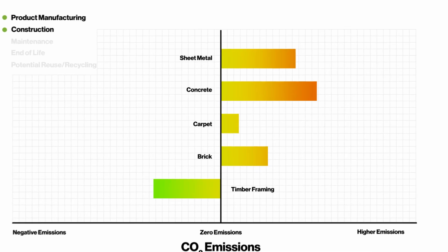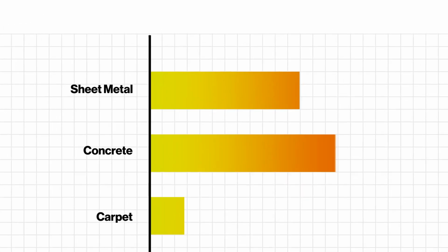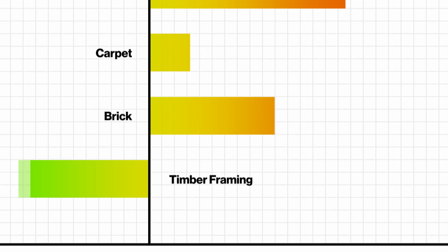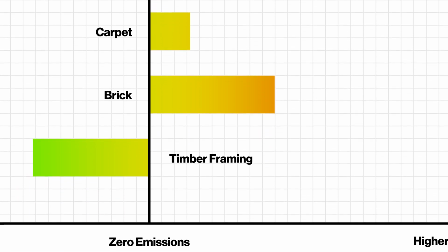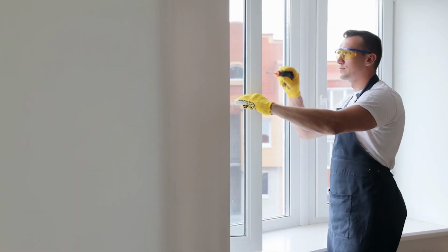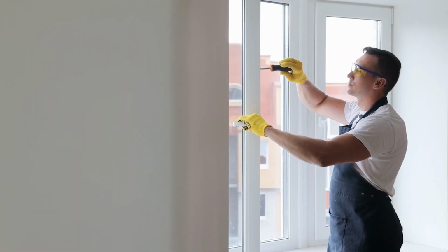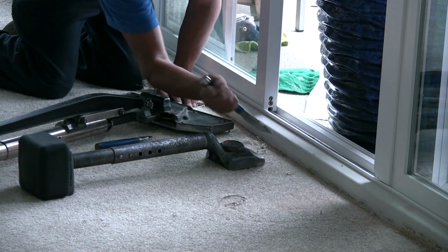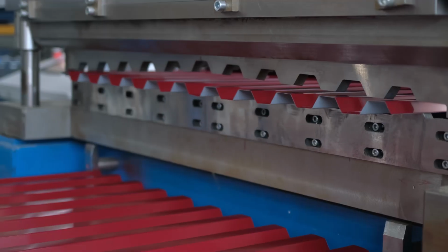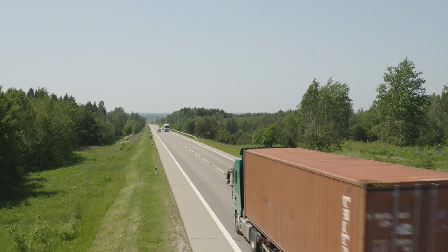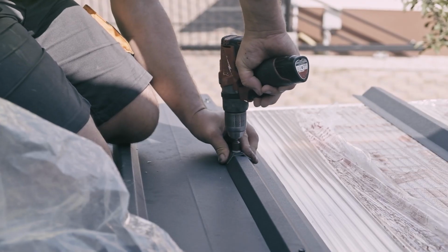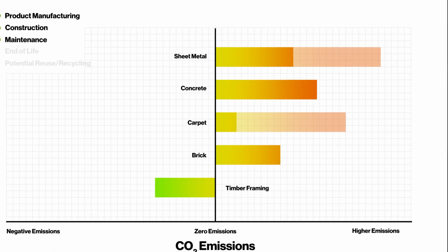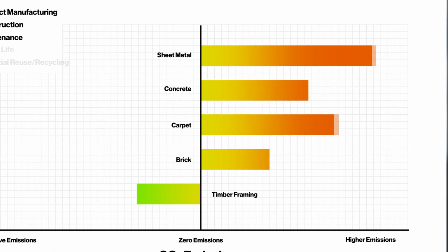During construction, the concrete slab, timber framing, and brick cladding have the most noticeable emissions for the house. From transport of materials to site, manufacture of materials that are wasted, and so on. Thirdly, maintenance. This includes replacing materials during the building's 90-year service life, which may occur multiple times. At each replacement, the material is manufactured, transported and installed, and the old material is recycled or disposed. As you can see, taking maintenance into account can have a major impact.